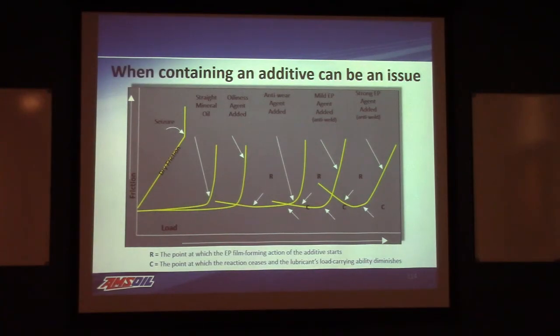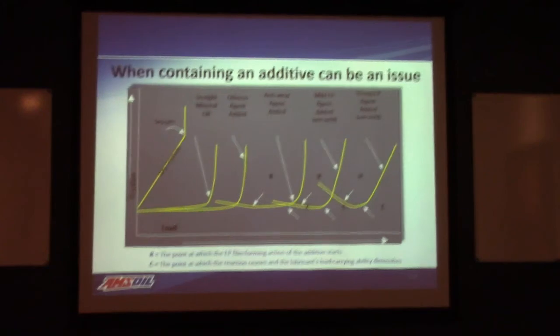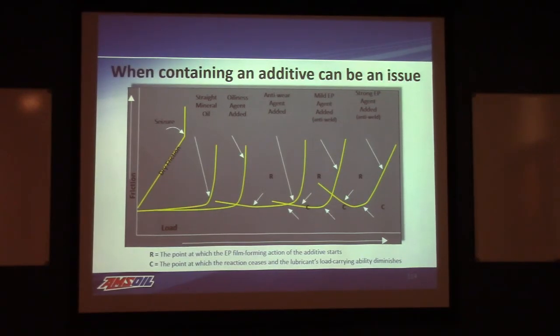You're just going to get the absolute minimum performance. Here's another one too. These are anti-wear and EP additives. A lot of people think, well, if I add these things in, it's going to help me out. It's only going to help you out if you really have an issue. Extreme pressure additives, for example, are generally used in gear lubes. Why are they used in gear lubes? Especially when we're dealing with hypoid gear setups, the sliding pressures and everything like that are significantly greater than found in an automotive application, and to combat that, they need a different type of chemistry. That same chemistry isn't compatible in an internal combustion engine.